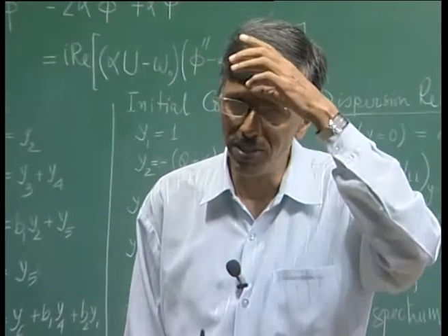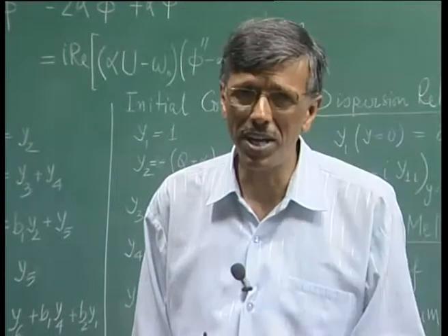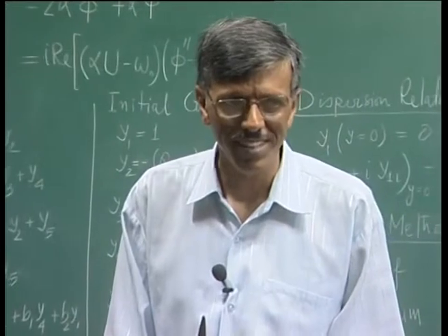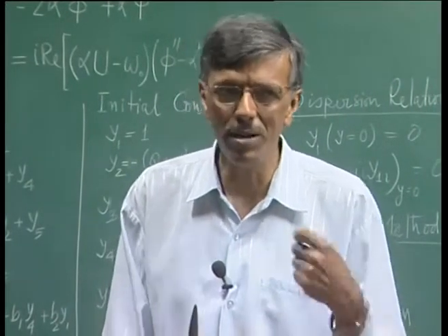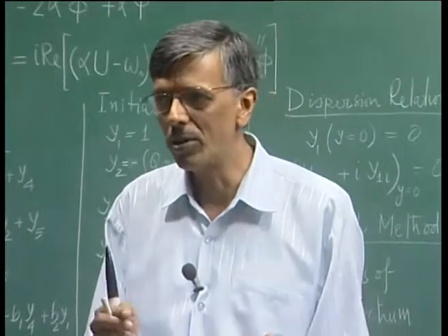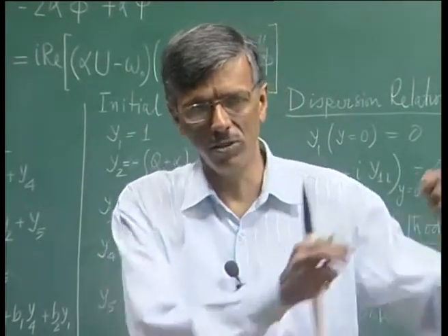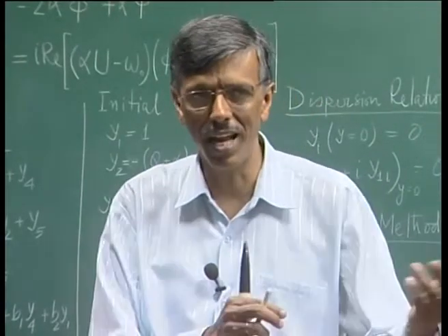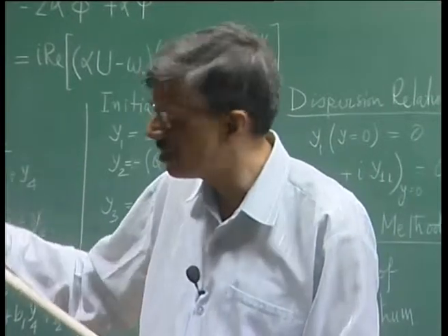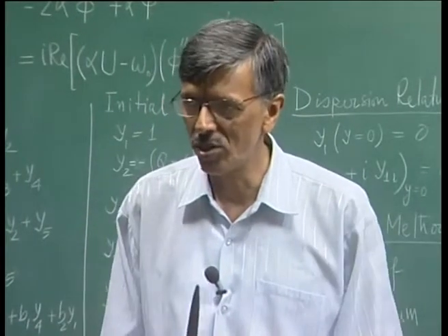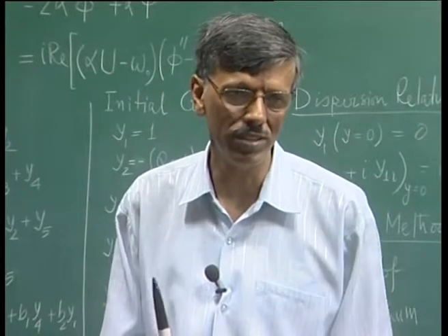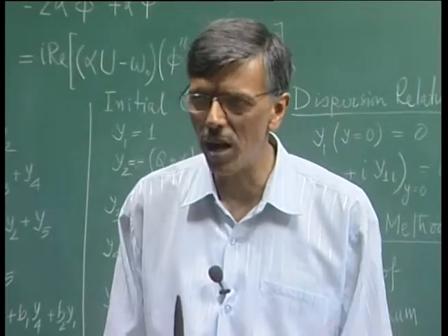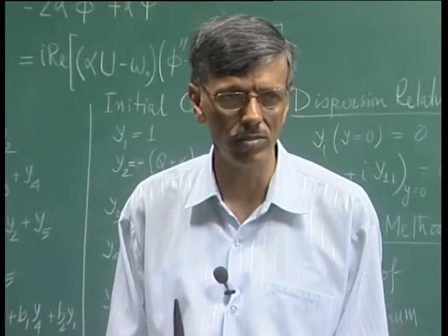that instability and transition in a flow, you cannot depend upon natural transition. It is very, very irreproducible, because I could take the same plate and go to another tunnel, maybe in the same lab itself, and I will do the same thing. I will see the oscillogram trace and I would see something different. Why? Because the disturbance background is different in different tunnels, right.